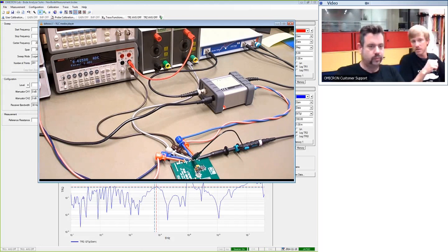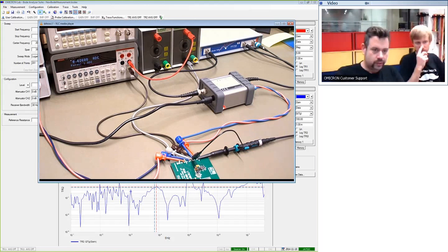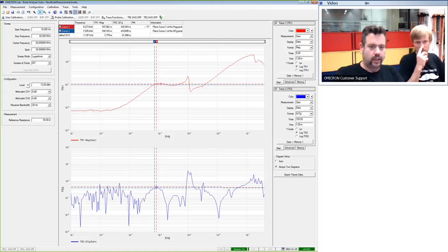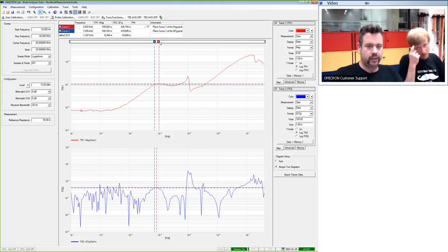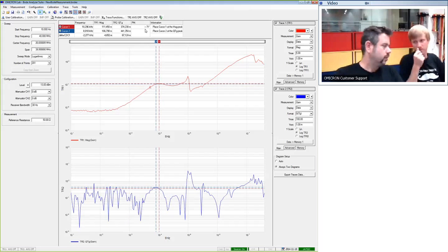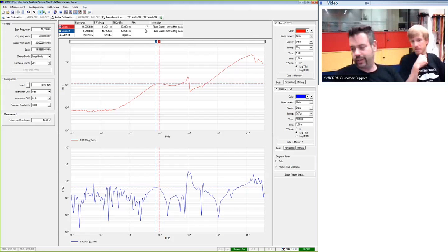Okay, so we have 600 milliamps, so you can see it here on our Keithley, and now you can see that we get a comparable picture like we had before when we had only the electrolytic capacitor connected. The peaking is reduced here, and even if I move here to the maximum and here to the center, we get this bigger than 71 degrees. So mission accomplished, I'd say. Definitely.